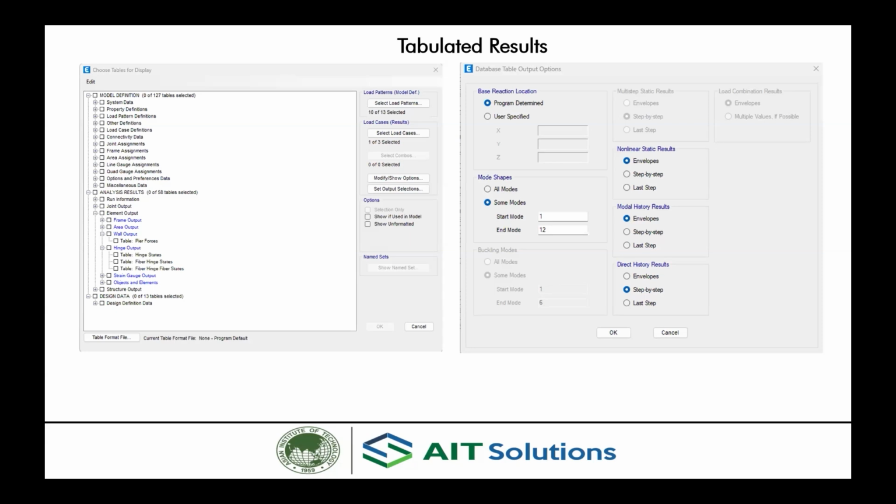You can see here, they give you the options to extract forces for walls, and hinge information, like what is the rotation, what is the state of the hinge, whether it has yielded, or whether it's beyond the strength loss capacity, what is the DC ratio for CP and all that. That will be checking the performance checks. But for basic hinge information, we want to use these tables to extract the information for all of the elements and components, for fiber hinges as well as for lumped plasticity hinges.